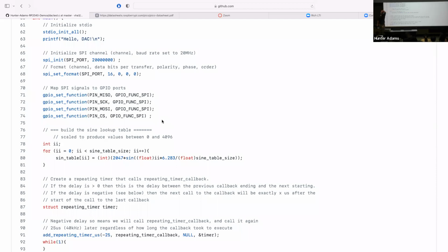I agree that usually if you look at the baud rate for a UART channel, it's either 9600, 38400, or 115200. There's a list of them. Where those numbers came from, I don't know the history of. Do you know, Bruce? They're based on how fast you could run a teletype in 1920, and that was 110 baud. They're all multiples of 110 baud. Interesting.